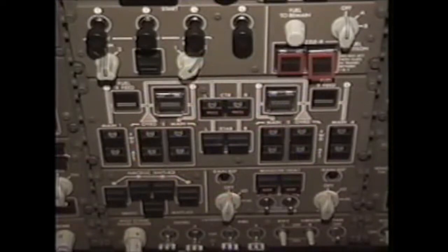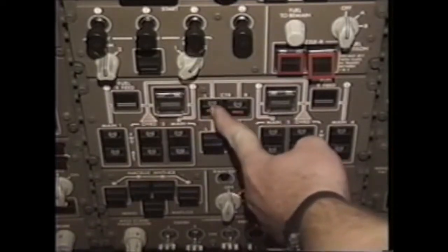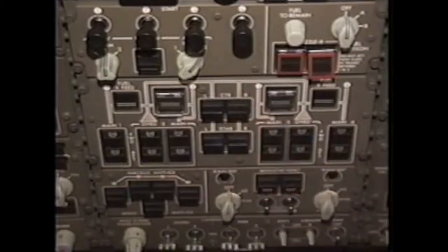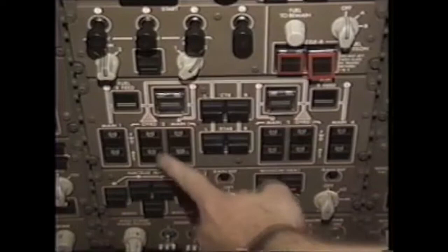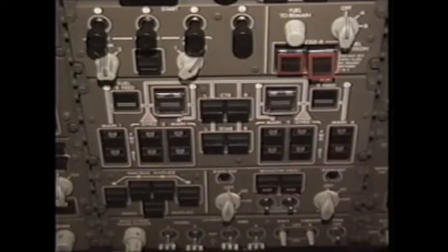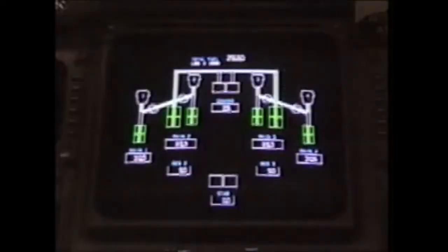With regards to the stabilizer, both the stab pump left and right messages are required before crew action. With regards to the center wing tank, either center wing override left or center wing override right message is required for crew action. Notify the other flight crew member that you are turning off both center wing override left and right boost pumps. At this time, the override jettison pumps in tanks 2 and 3 are now feeding all 4 engines. This can be verified by bringing up the fuel synoptic.